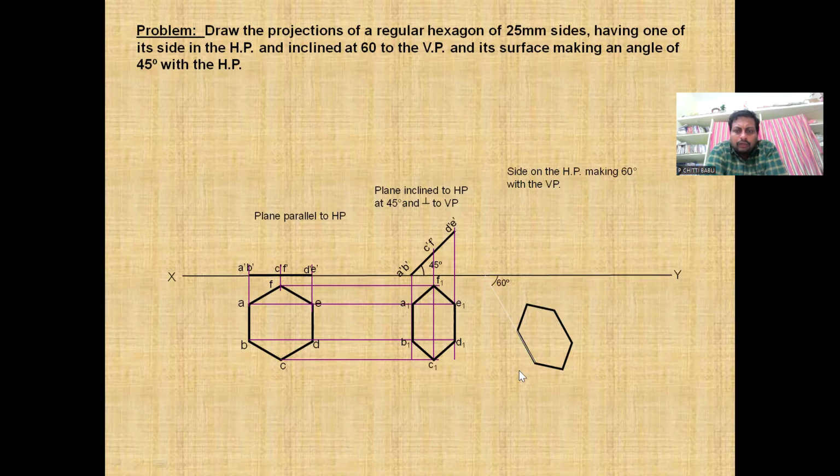Then we need to draw exactly perpendicular lines. Then you locate E point and D point. After that, take AF as the radius, A as the center, and do the arc here. Similarly, take EF as the radius, E as the center, and do the arcs. That intersect point we locate as F.